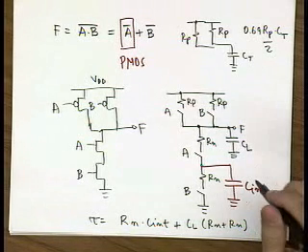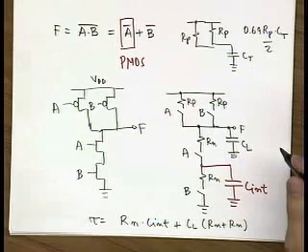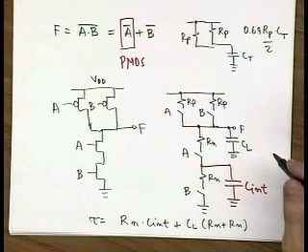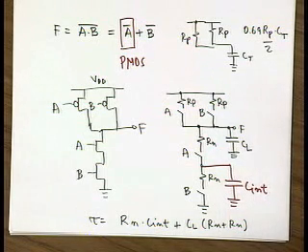So the conclusion from here is, for complex gates, delay is very dependent on the input patterns. Depending on how your inputs switch, you will have different pull-up and pull-down configurations, resulting in different delays.